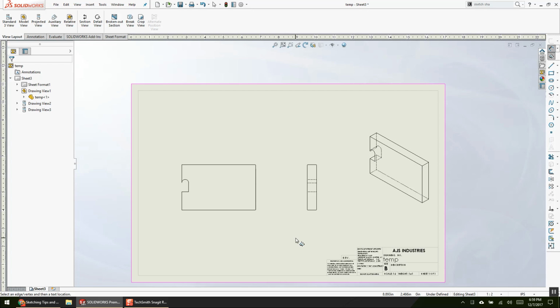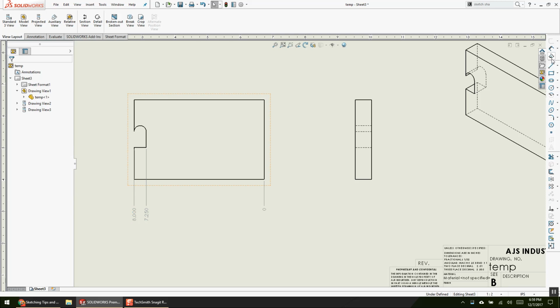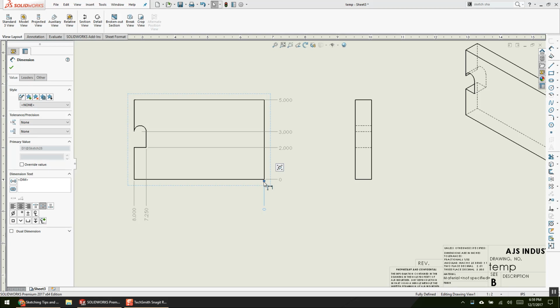So when I come in the morning and I tram out my mill and make sure it's all square, and I find my zeros, I'm going to take my edge finder and find the back of my vise and the side of my stop. And then a smart engineer who has a degree gives me a print like this. And what's the mill guy going to do? Take the print, flip it 180, interpolate all the dimensions invertedly, and attempt to make you a good print.